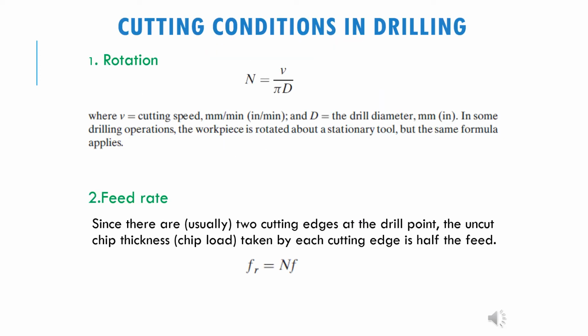Here is the cutting condition in drilling. The equation is still the same: n equals v over pi d for the rotation, and for the feed you still use the same equation, which is fr equals nf.